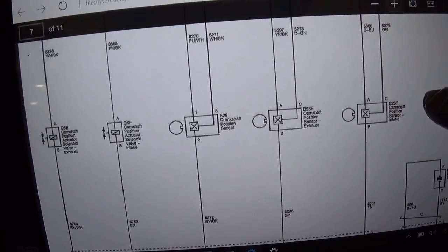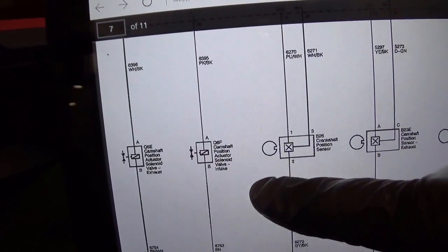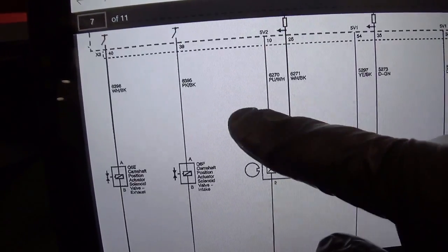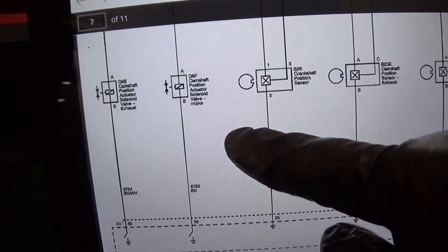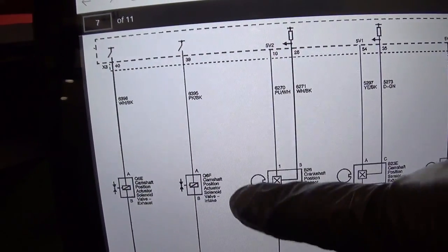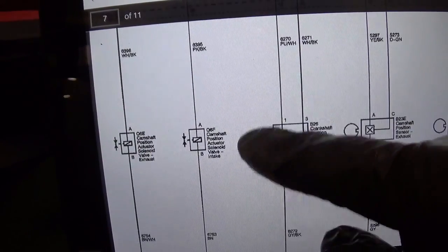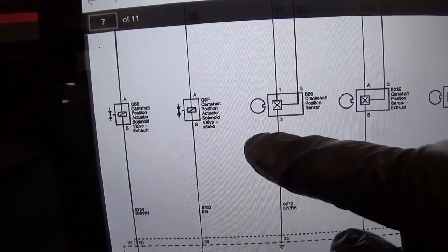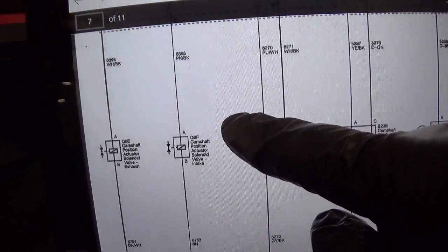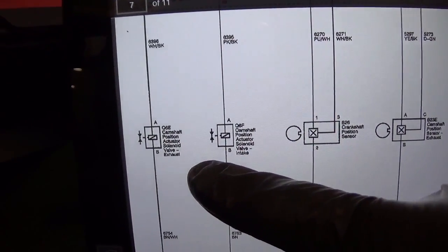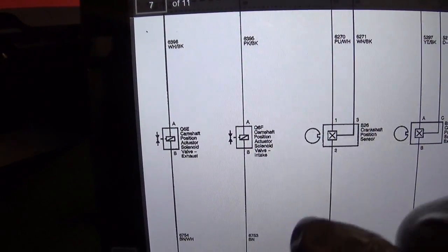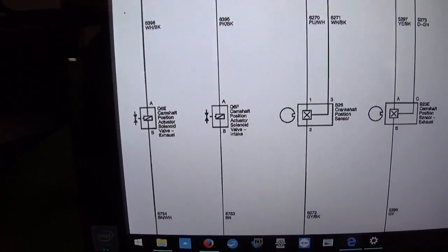So that's 3 channels. Then these solenoid valves look like both sides, the power and ground side, are tied into the engine computer, so it can actually switch the power side and switch the ground side. So it's not just a simple power or ground side switch solenoid. So again, we can probe either or. We know the exhaust valve is supposedly good, so we can get some known good signals from there and then move on to our intake.